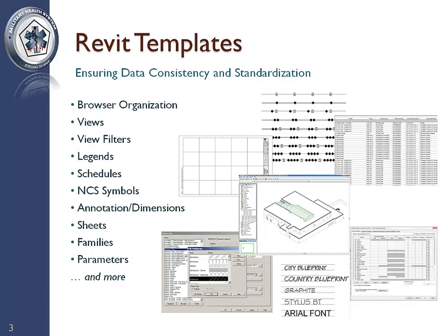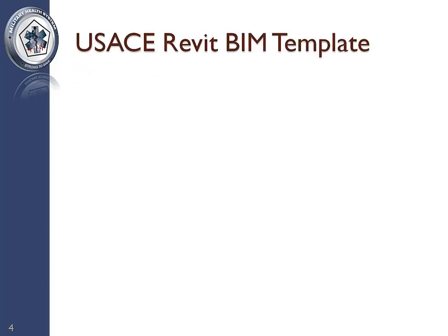Building Information Modeling, or BIM, with the Autodesk Revit platform offers the capability to configure, save, and deploy a standard working environment via template files. These pre-configured Revit files can significantly minimize the time and effort required to configure and coordinate Revit projects. They can contain standard elements and details, naming conventions, schedules, views, sheet layouts, output settings, and many more standards to organize project development.